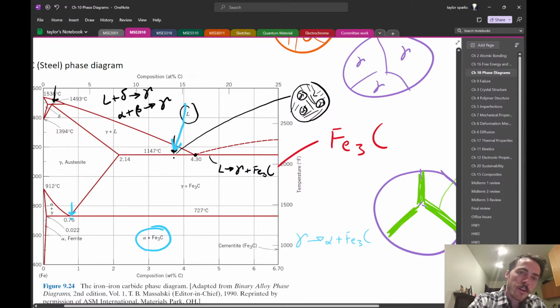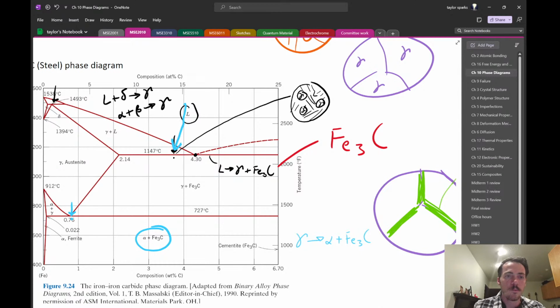At this point right there, it looked to me, just eyeballing it, that it was about 3/4 liquid. Well, what if the density of the liquid is wildly different than austenite? Then technically you'd have to calculate the volume fraction if you knew the density. That's more work than I'm going to expect you to do. A simple sketch suffices, but for a complete answer, I'm always going to ask for the fraction of the phases and what is their composition.